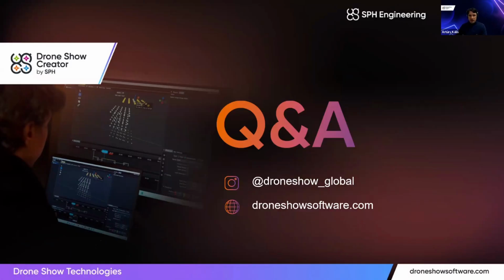Let's see if we have something that would be interesting to answer live. Okay, yeah, another question about the distance between drones. So yeah, this is actually a good question. We advise first of all to go, let's say 2.5, but most of the shows are being done at a 2 meter distance. So yeah, I'd say 2, or you can go even a little bit less than 2 if you feel safe and you're confident about your fleet. But general guidelines would be 2.5 to 2.